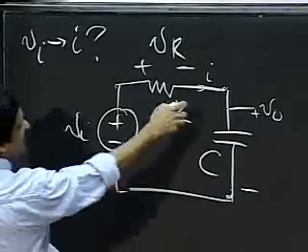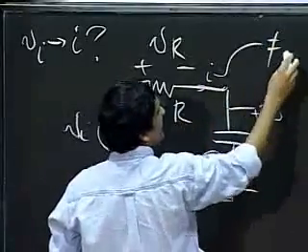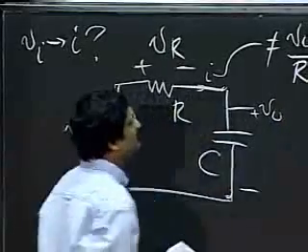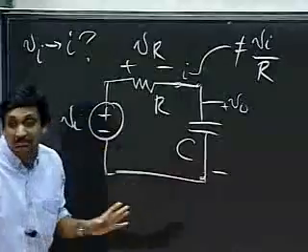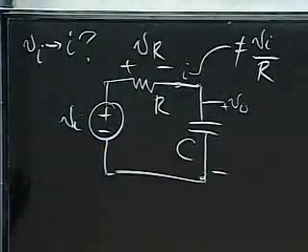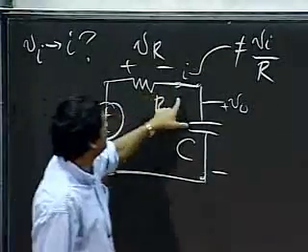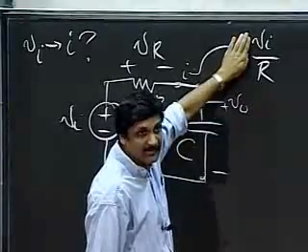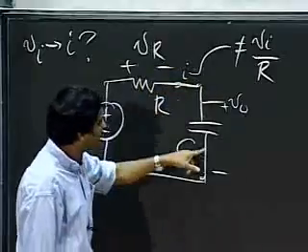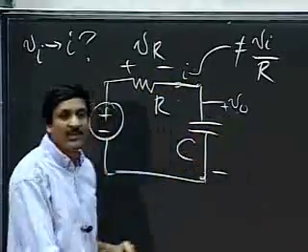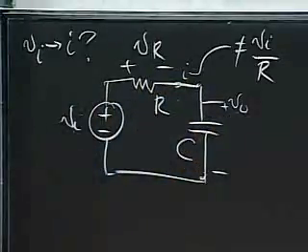But it turns out that I here is not equal to VI divided by R. If I was VI divided by R, somehow, okay, I'm done. Okay, if I was VI divided by R by some magic, then I've converted my voltage to a current. I feed that current through my capacitor, and VO is my integral that I'm looking for.